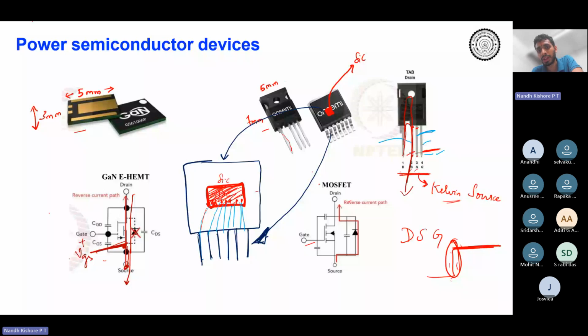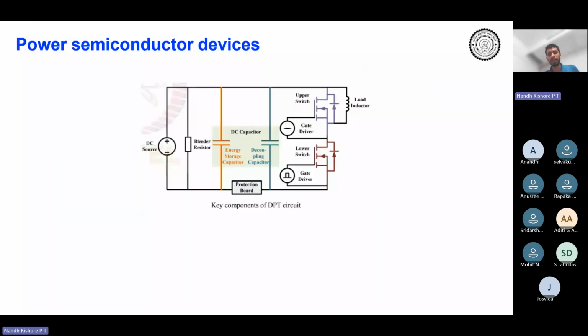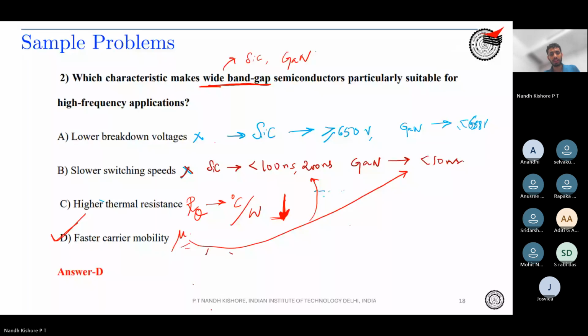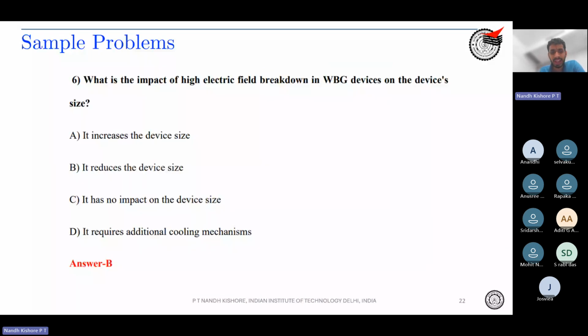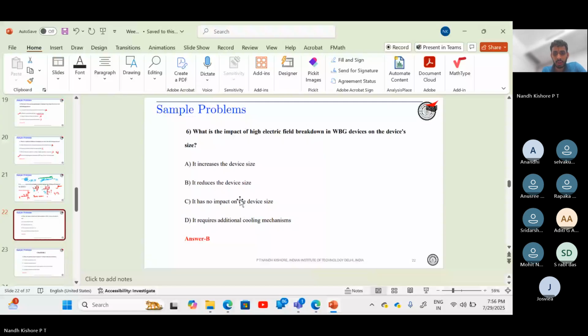Just from the purpose of gate driving, in terms of gate to source voltage, where you give your gate source voltage, it is preferable to give it at the Kelvin source, because the Kelvin source is physically near to the gate. So the loop inductance is lesser. Okay. So the next question: is it fine? Does this answer the Kelvin source problem? Do you understand what Kelvin source is now?